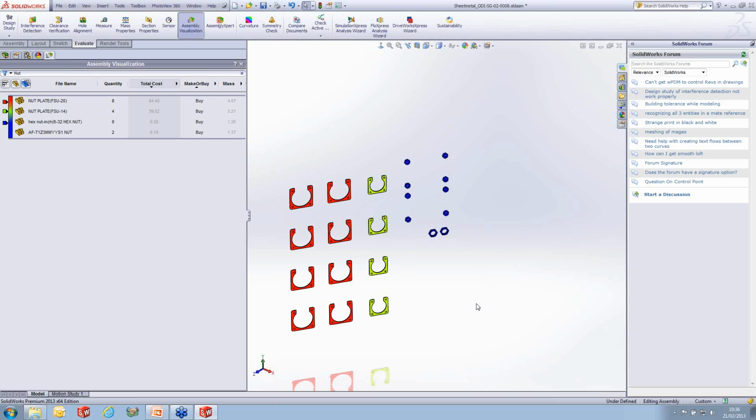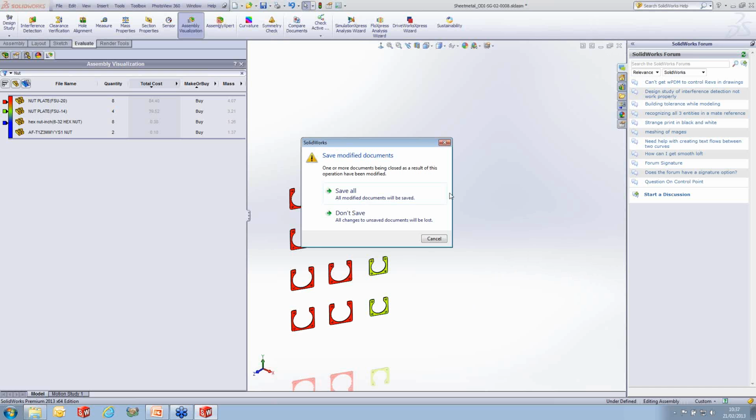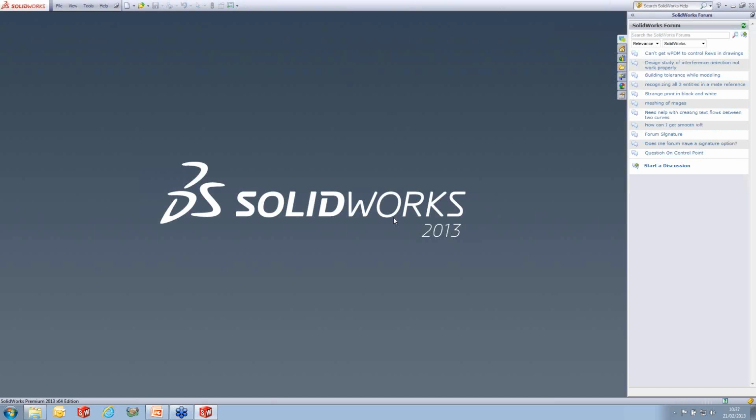Okay, so hopefully that gives you a good idea of how you can use costing within all levels in SolidWorks, and specifically for the sheet metal designs. You can see that most of the work is actually put in within the template editor and actually building that up. Once you've got a good template built up, your costing wizard will work well. But if you haven't got all the items added in, you can manually apply custom costs to particular parts of the design.